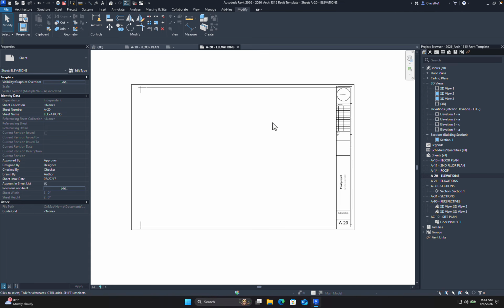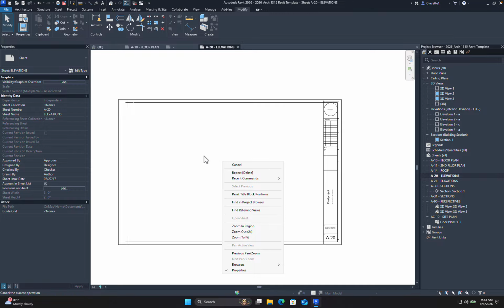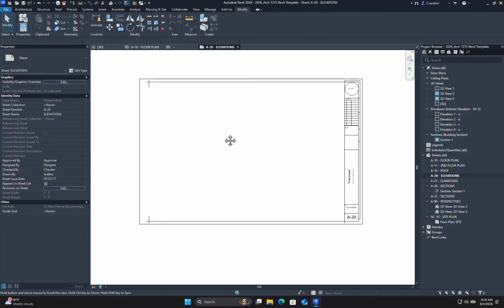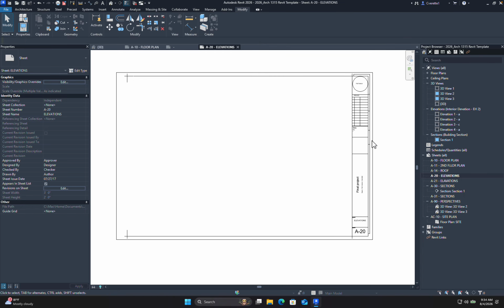It's also very different in terms of moving around. You'll notice your middle button, you have to have a mouse for this, right? You need a three button mouse because you'll use that to, of course, move. If you right click, it'll actually bring up a regular right click window, right? I've even set sometimes my Rhino to be more like Revit. That way, going in between these programs, I don't feel disoriented every single time. I would say it's easier to change in Rhino than to change in Revit, so very often I actually change it to a standard of Revit.